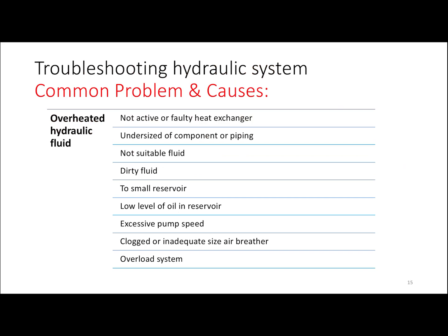Right. The next cause is a clog or inadequate size of the air breather. And then the last one is an overloaded system. Okay, so an overloaded system is related to friction. If friction is high, the temperature is also high, then the hydraulic fluid temperature is also high.